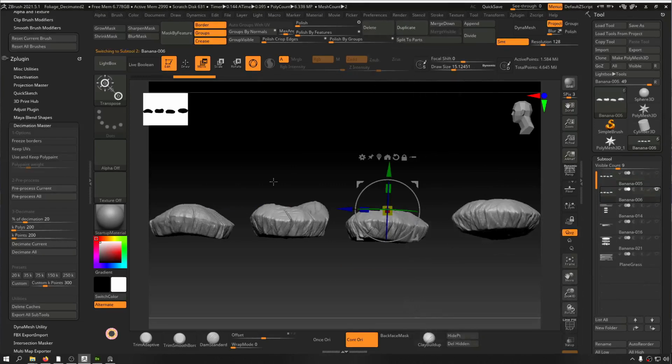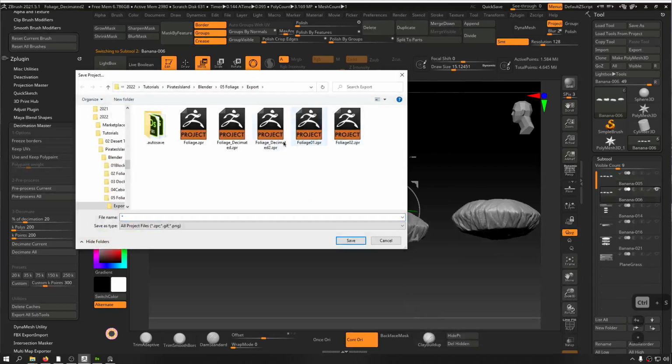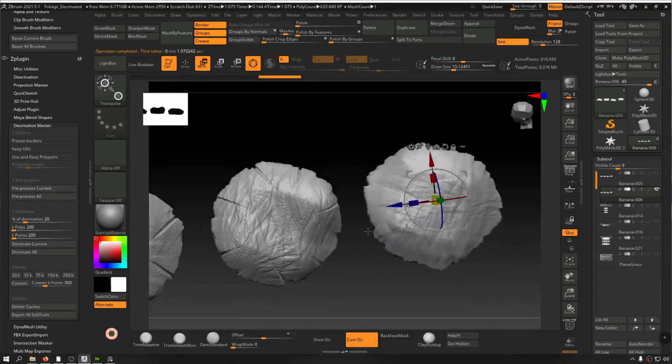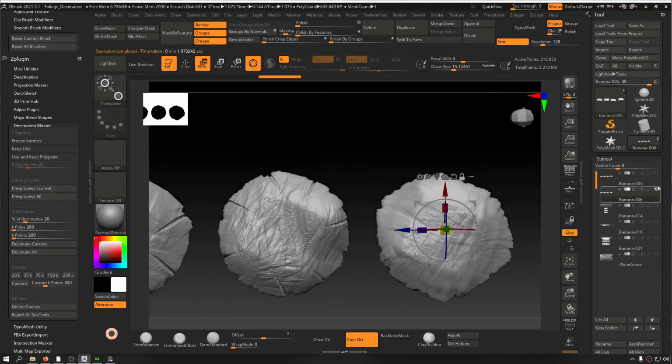Let's hide the first version, which is the high poly, and try to save it first. And decimate this. We're going to bring this down because this is going to be a low poly, and we're going to duplicate this. For example, for a tree, we might take something like 100 of these to make a tree. So I'm going to bring this to a reasonable amount. So let it calculate, and now decimate again. We've come down to this number, but we can go down more.